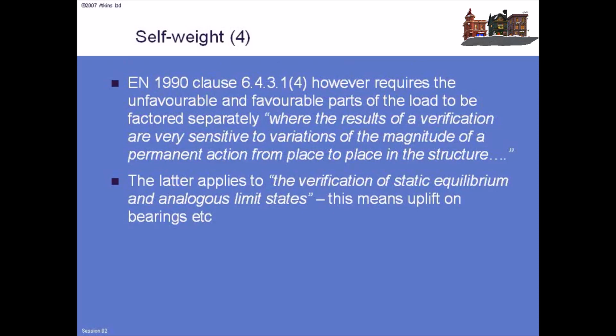So although this isn't very clear, it's probably slightly clearer than it was in BS 5400, which said nothing at all about it. And a lot of engineers, if they were worried, did start factoring spans differently, and they did start applying gamma F3 to one span and not the other. At least this is clearer, even if not completely clear.